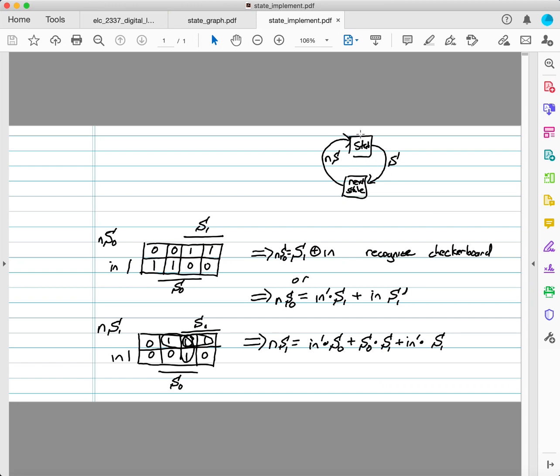Now, the reason I do that is we go back to remembering, when we first started out, I said for all of our sequential designs, we had a state section. You can see this in this little upper right-hand diagram I have here. We have a little square box with state in it. That's all my registers. And what comes out is the current state. And that goes into the next state logic, which is a combinational circuit. And so I can't have it come out as S. I have to give it another name, but it's connected to it. So next underscore is a good way to do it, or N of them. If you use a little N first as negation, then maybe you want to say next underscore or N underscore, whatever works.